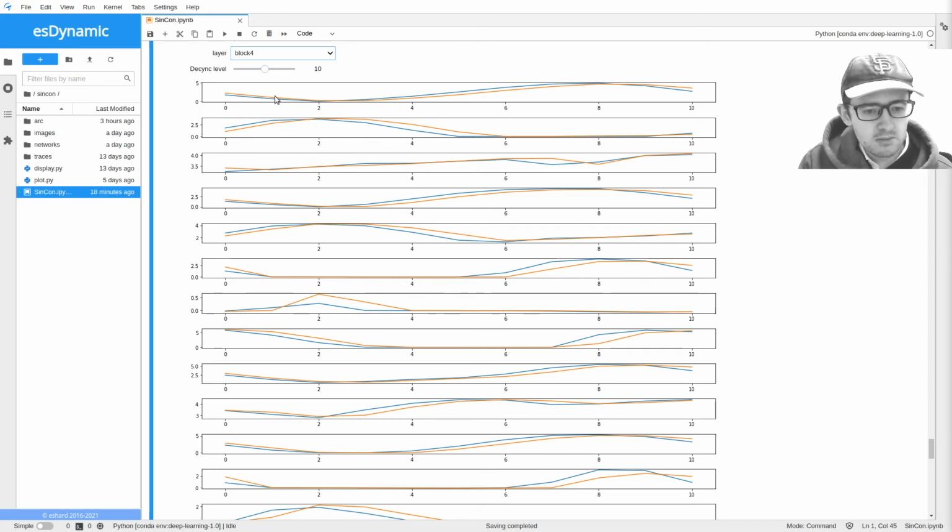So this example illustrates how the translation invariance works with CNN, and why it is able to efficiently process side-channel traces that are desynchronized. And so, as I explained earlier, because desynchronization is one of the biggest challenges in side-channel, it's very interesting to have neural networks like CNNs that are able to handle desynchronization and still be efficient to classify side-channel traces. And it's very interesting because here everything is automatically done by the network. The attacker, the analyst, does not need to resynchronize the traces manually before the attack.